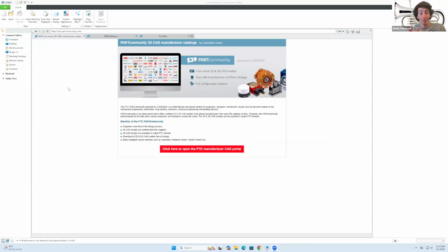And now we need to start doing things. In general, whenever you go to a CAD software, as in this case, you'll be creating things that are called parts. Essentially, you just draw, you make a cube, you make a triangle, and you have a 3D object out of which you'll be able to subsequently build assemblies that consist of multiple parts. But in order to make a part in the first place, you need to make sketches. And sketches, as we'll see in just a moment, define absolutely everything. It's all of the features that correspond to a part. So how do we do that?